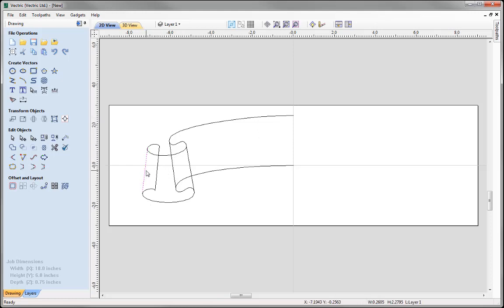So I don't need these connecting lines anymore, so I'm just going to delete those. Okay, so just select it and delete it with the delete key on the keyboard. And the next thing that I need to do is I need to look at cutting these two vectors at the apex of each one of these curves. And the reason for that is that we're going to look at joining them from the top to the bottom so that we can create closed regions in order for us to crop our components back to once we've modelled the parts using the two-rail sweep.